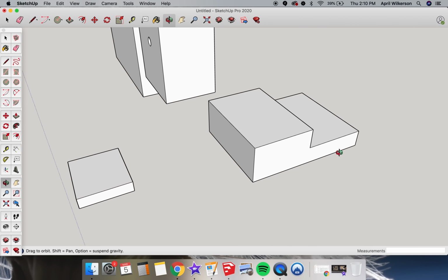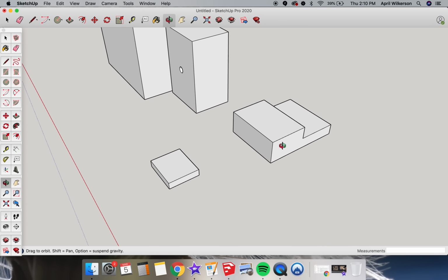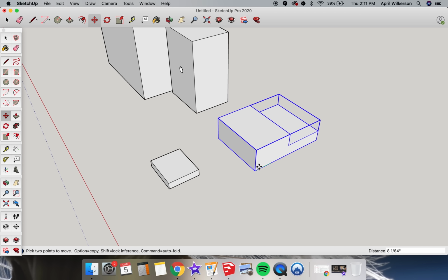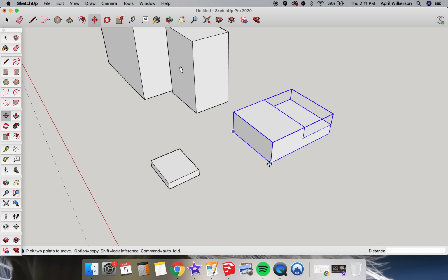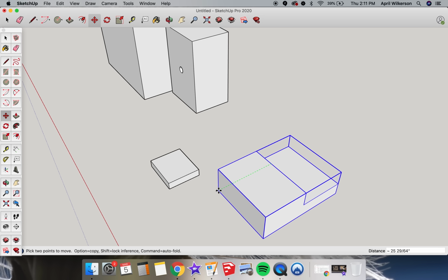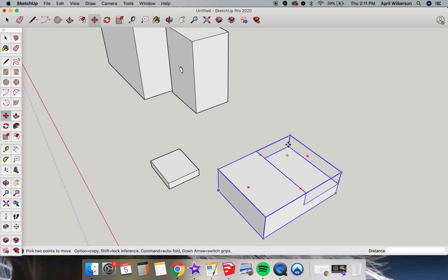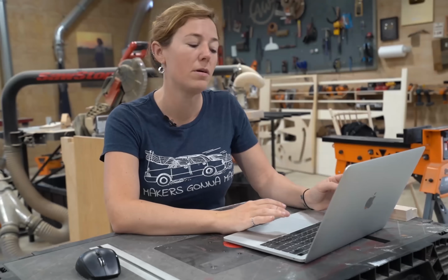I'm going to go ahead and cover the move tool, then come back to components. The move tool shortcut key is M, and it allows you to move things around the space. You click once to start the tool and pick up a part. Move your mouse where you want the part, then click a second time to drop it. One huge thing to remember when using this tool is to always grab by a corner or an edge. This is a little thing, but it's valuable for fast and accurate modeling.